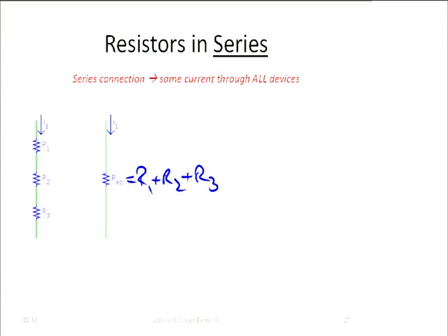All right, why is that the case? Well, it's the case because of Kirchhoff's laws and Ohm's law, but we can boil this down to the fact that the resistance of several resistors simply adds up if these resistors are in series. Why are they in series? Well, it's because the current through all of them is the same. Okay? So series connection, important to recognize.